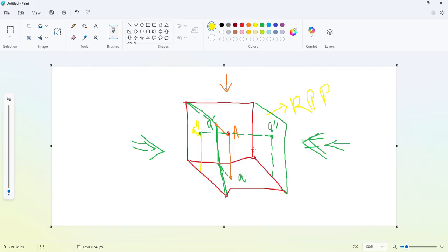And if we consider this point from the right side, then the right side view will appear on the left projection plane, which is this one. So this is LPP. From the right side, the right view will appear on LPP, and from the left side, the left view will appear on RPP. Left projection plane, right projection plane. Now we have to plot these side views again on the same XY line. So there are some steps to be followed to plot this on the XY line.